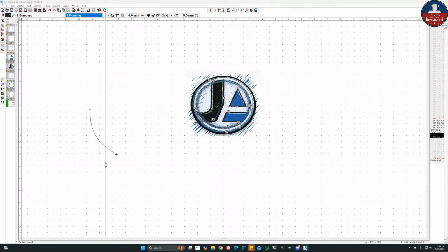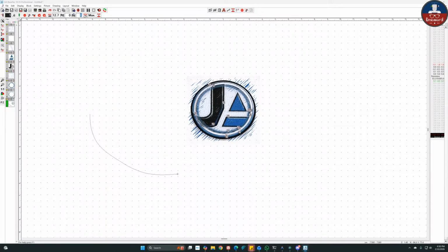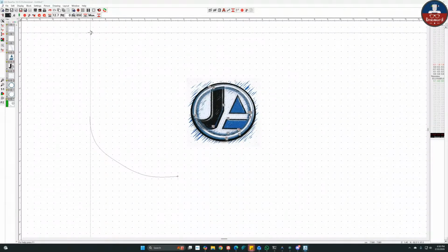And it really starts to shine a lot when you go into pairing it with the machine. Because like here I can actually say, you know what, I'll put in an RPM command. I want my machine to run at 650 stitches a minute right here because I'm doing small text. And then at the end of that, I can hit the button and make it go back to max speed.